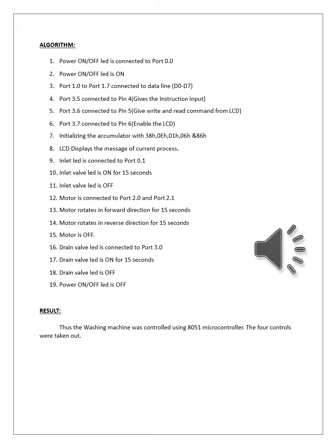You may ask whether we have to connect only to these ports. Not that. In my simulation I am just going to use these ports for connection. Any port you can use for any purpose. Here we have 4 ports, and each port has 8 lines, so in total 32 lines will be there. I already indicated the operation: inlet valve for 15 seconds, washing for 30 seconds, and drain valve open for 15 seconds. So in total it is 1 minute of operation.